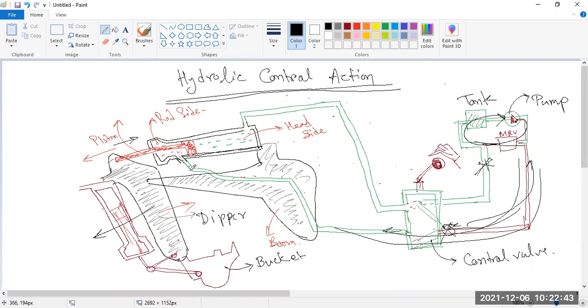now? You can see this is the hydraulic JCB. If this rod portion goes to the outer side, how is it possible? The fluid is generally petroleum fluid, which has some specific gravity. If this valve controls which channel the pump will push this fluid into, and if in this area the fluid is greater than this area, then it will create a pressure on this piston. Then the piston will go to the outside.